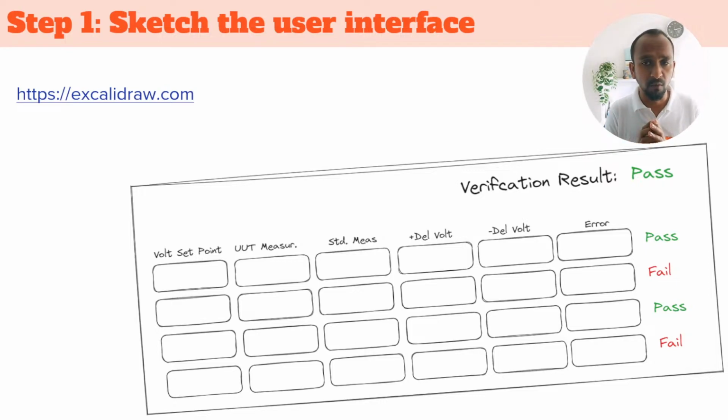For example, for a 1 volt set point, after all the resistance of the wires that connect the instruments, I might actually be getting from the power supply 1.0001, some 0.1 millivolt extra on it. So from that 0.1 millivolt change, how much would I expect my UUT measurement to vary, what level of variation it could be.